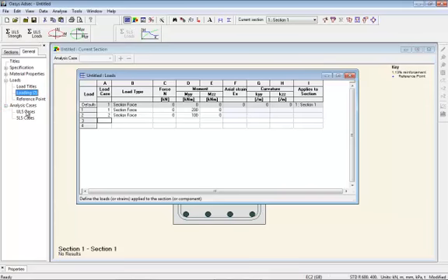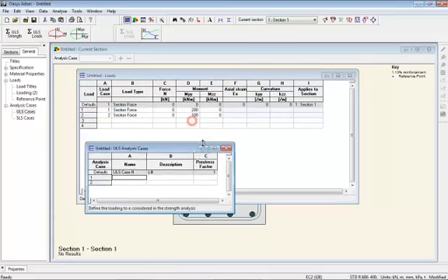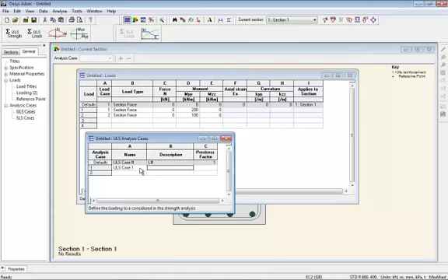And then an ultimate limit state case, which is going to be 1.35 L1 plus 1.5 L2. And I could have pre-stressed some of the bars, but I'll leave that off. That's 1. So with this ULS analysis case set, I can then do a ULS load or ULS strength check.